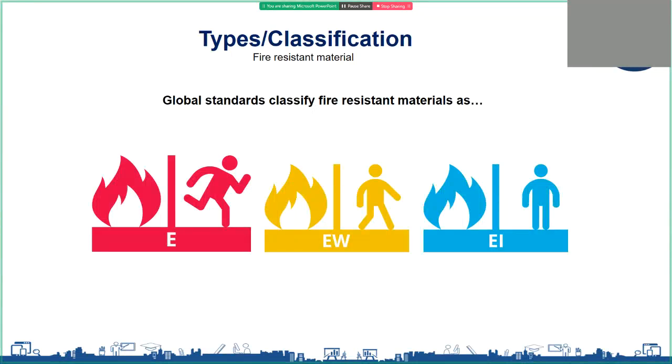If there are any combustible materials on the other side of the fire, these combustible materials might start to heat up because of this radiation, and beyond a certain point they will ignite. So this is what we call indirect combustion. Without any direct contact with the flames, the materials on the other side get spontaneously ignited just because of the radiation. So we need better protection.